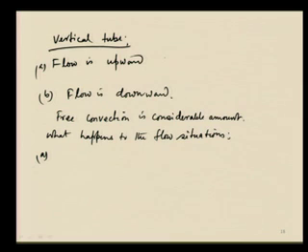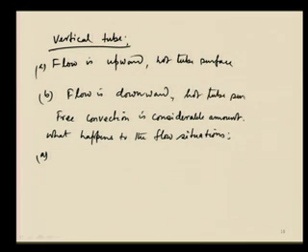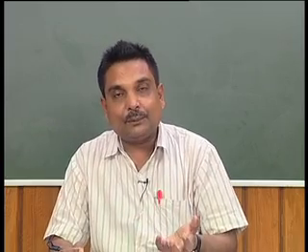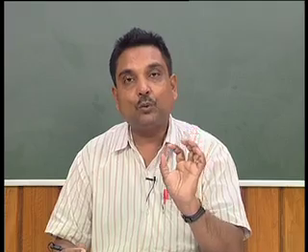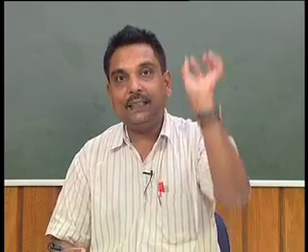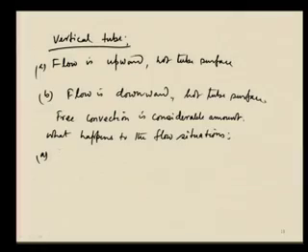For the first case, the flow is upward and it is a hot tube surface. So, in the very first case, the fluid will be flowing upward, and because of natural convection also the flow will be upward. So, the natural convection flow will be adding to the flow of the fluid. This is called aiding flow.